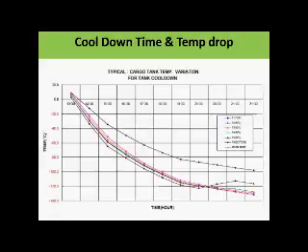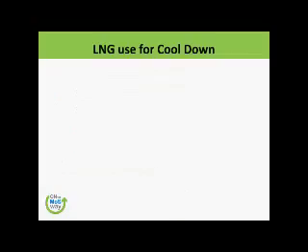In the beginning, we will see a very sharp fall in temperature, but slowly and gradually this will go on a very easy curve, and nearly at minus 161 degrees it will be fairly steady. So now, rather than using any refrigerant, we are using LNG for cooling down itself. LNG does have the properties of a refrigerant.